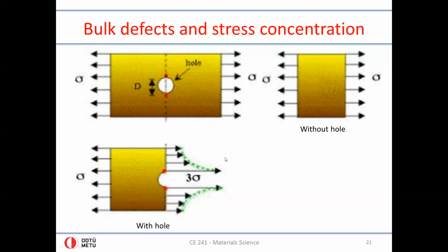If you had a hole, it would be in amount equivalent to what is being applied on the left-hand side, pulling the half of this plate, this imaginary half plate, in this direction. And the reason for this is because if you pull with more force on the left than on the right, then the material will move towards the left, or the plate will move towards the left. So you need to have some sort of force balance, some sort of pulling balance.